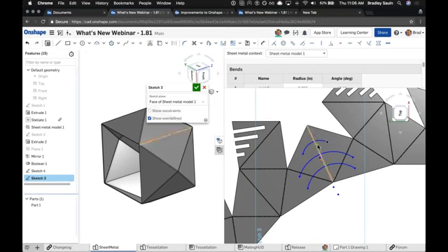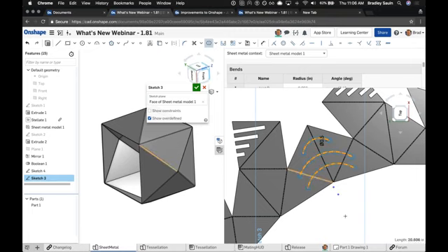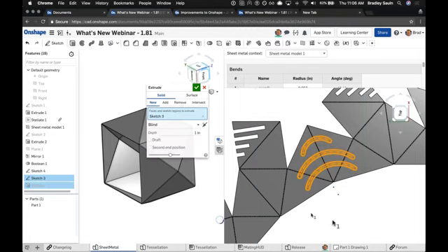So I've got some nice arcs in here that I may want to perform a slot feature along. I'll quickly select each one, convert them to construction lines, and then hit my S key to come in, and I did not add my slot feature. That's okay. We'll grab it here from our main selection list and get them thrown in here. Now I'll hit Shift E to go to my extrude command.